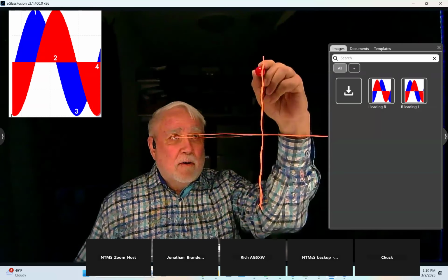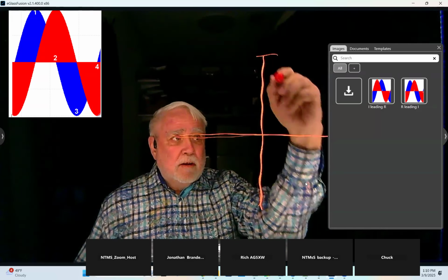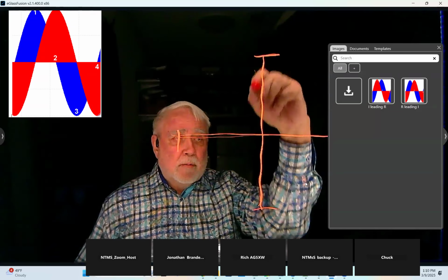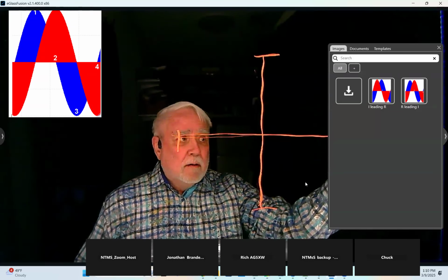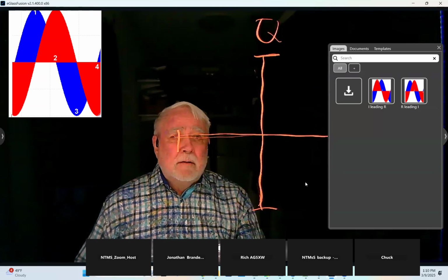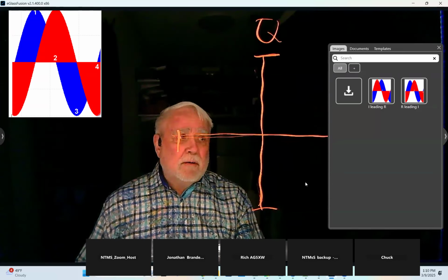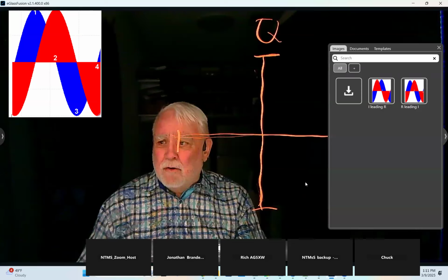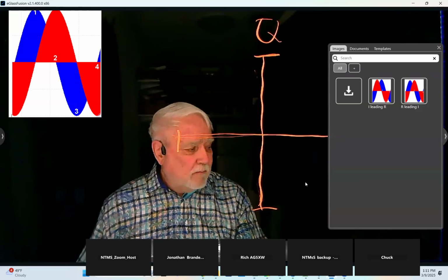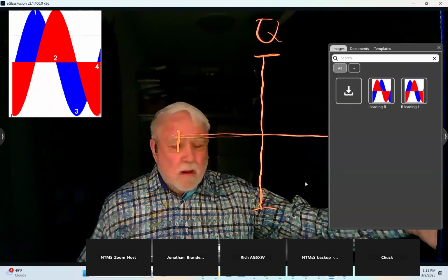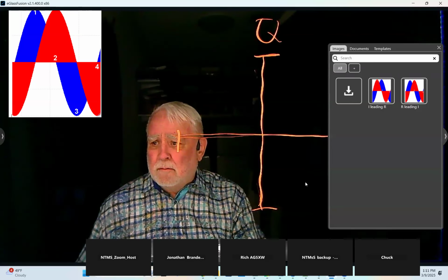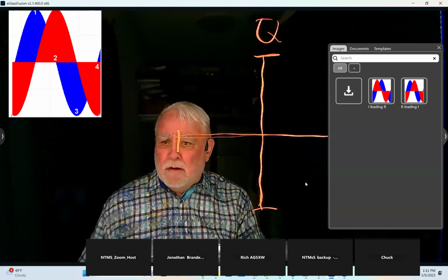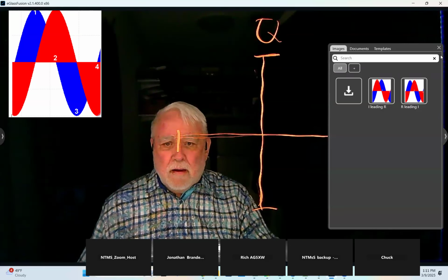Let's say that these values are 1, -1 and -1 here on what otherwise could be a Cartesian plane. This is our I axis, this is our Q axis. And for a positive signal, I've got this pair of sinusoids, which was a picture taken out of GNU Radio with a stem plot turned on. I've got it numbered with crests and zero crossings. We could put numbers by these, and we did before. So let's go through that again.